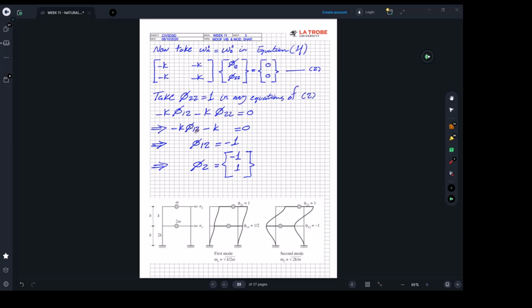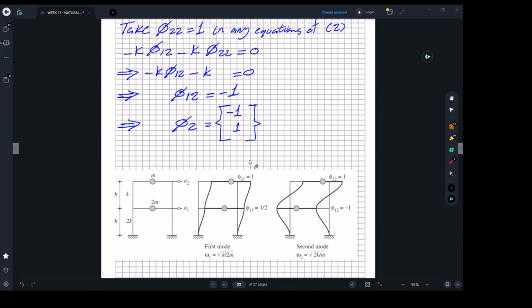Understand the difference between the first mode and the second mode, in terms of their properties, their significance, their engineering application. As we said, usually the first mode will be more severe, and there are a lot of cases where we found the first mode shape is more critical, so we try to stiffen up. Stiffen up means we change the stiffness. We change all those values here. By the time you change the stiffness, you are changing everything we have here. If you double it, if you replace steel with concrete, if you use composite steel instead of hollow section steel, that's where those decisions can come, right?